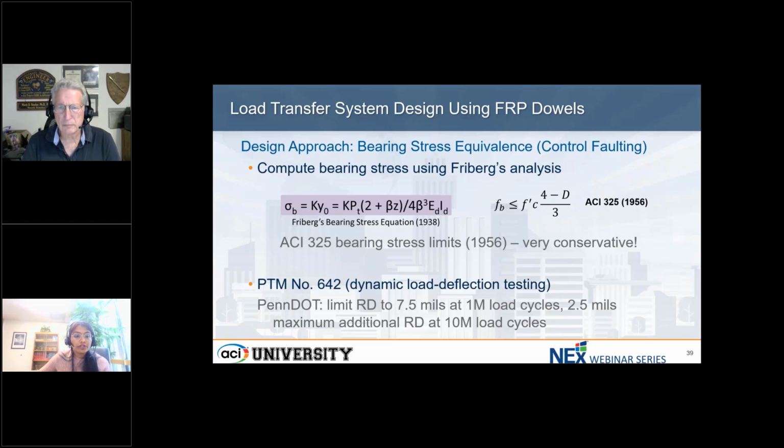So you also talked about the GPR system. It's not a question, but it's a concern, or maybe you want to add something to it. GPR and ultrasonics are unable to locate GFRP bars because the properties they focus on are nearly the same between concrete and GFRP. GPR may be able to see it occasionally, but it is not guaranteed.